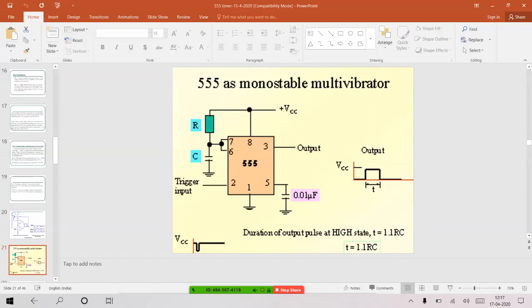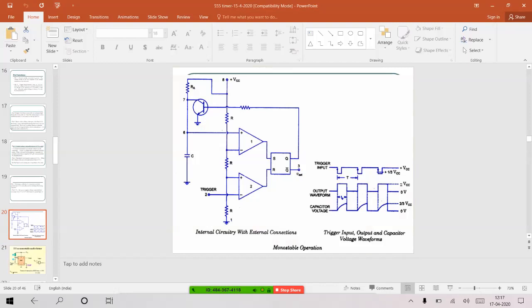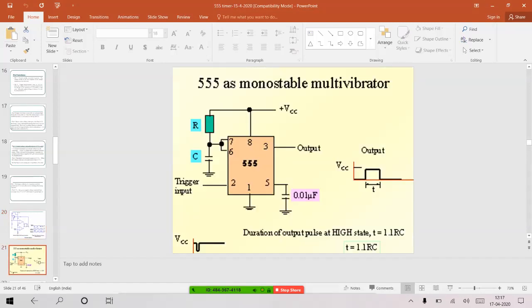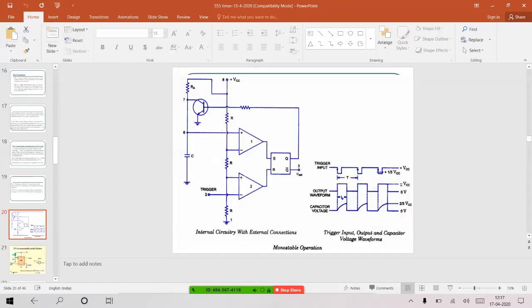So this circuitry, IC wise, how it looks, the IC configuration when you do like this, you'll be able to achieve the same. This is in block diagram form, and the same thing when you write in IC form, you directly utilize the IC pin details, and you connect the circuitry directly and generate these pulses. Simple to look. If you remember the pin numbers, that is enough here, with the two components R and C extra connected to the IC. Otherwise, the rest remains the same. But if you know the internal block diagram and working, understanding is easy, and no need to remember things here.